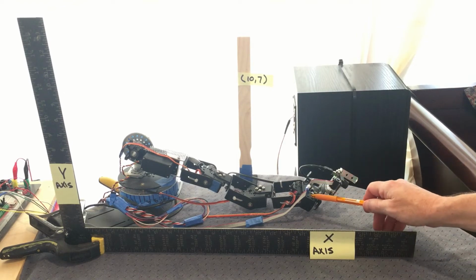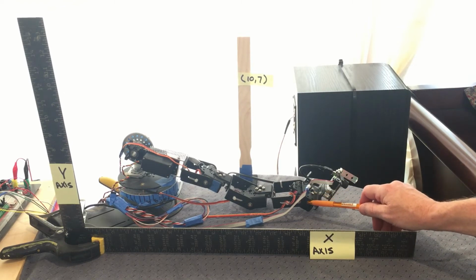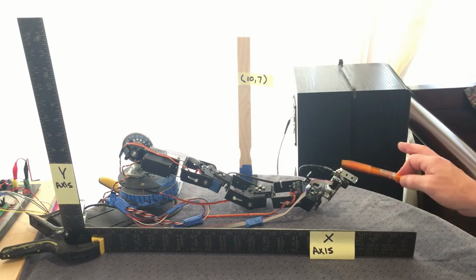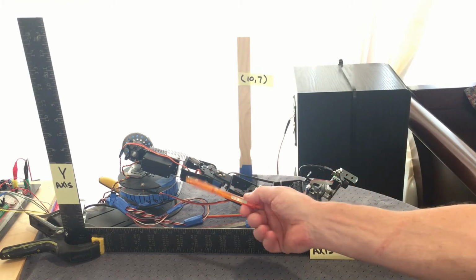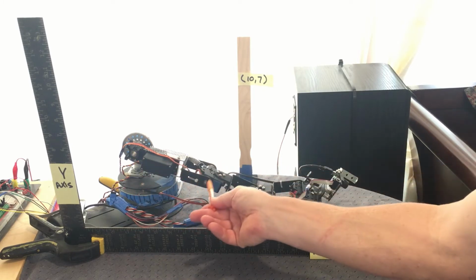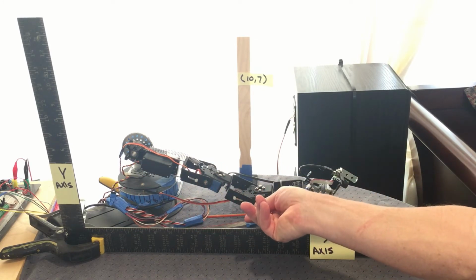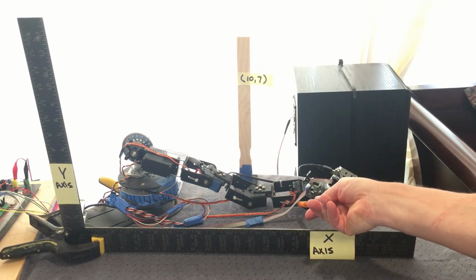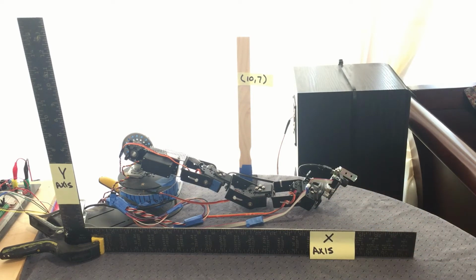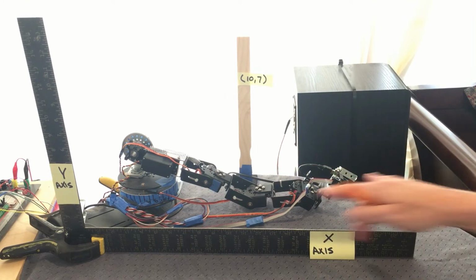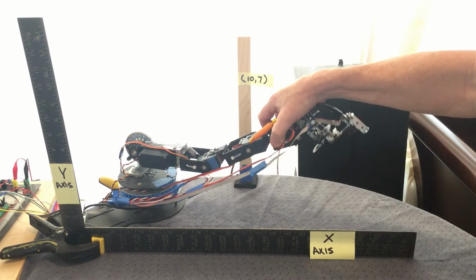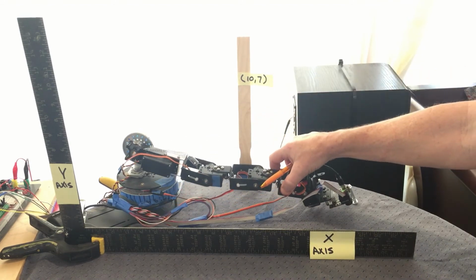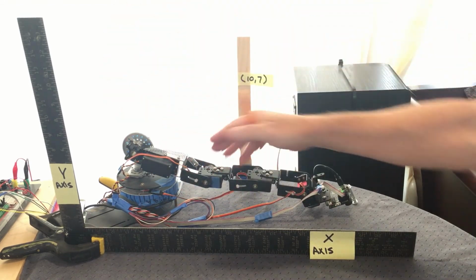Also, I do not take into account this last gripper servo because it operates a camera or some other device. So that's not part of the calculation. So I'm only doing 3 degrees of freedom. I'm doing from this leg, which is 6, this leg, which is 4, and this last leg, which is also 4. So how you can have multiple servos out here. You can have as many as you want, and they can also pivot, which I don't take into account, in and out. I'm only dealing again with a 2-dimensional plane, not 3-dimensional.